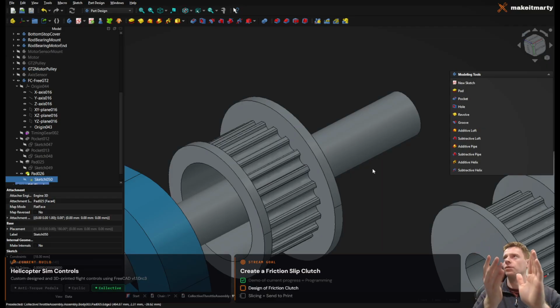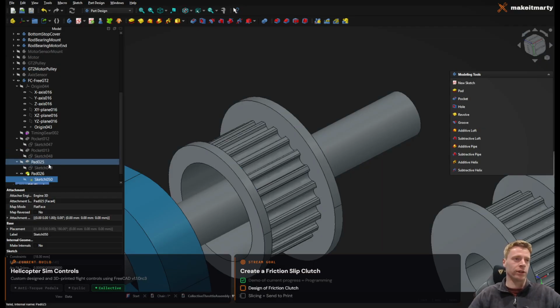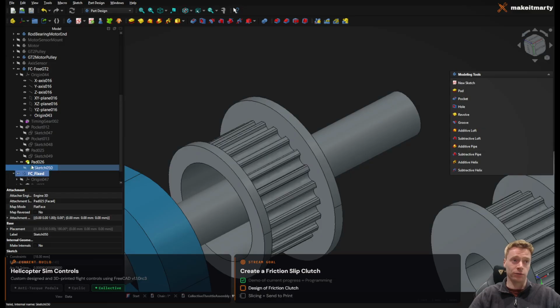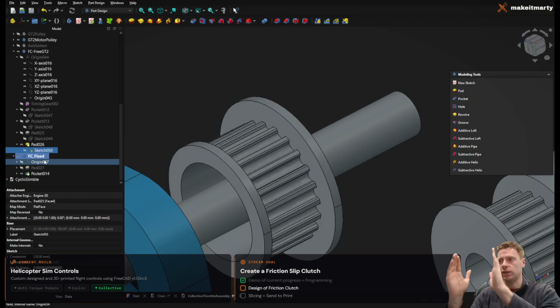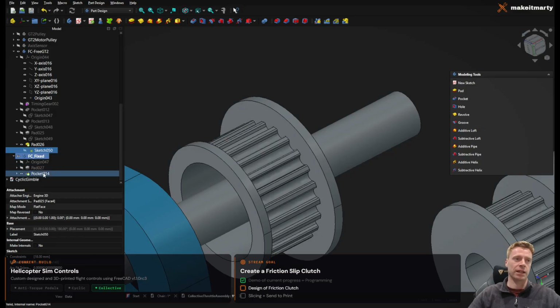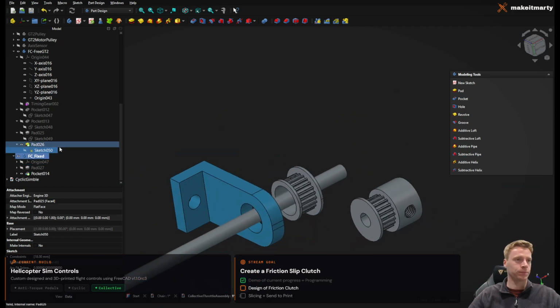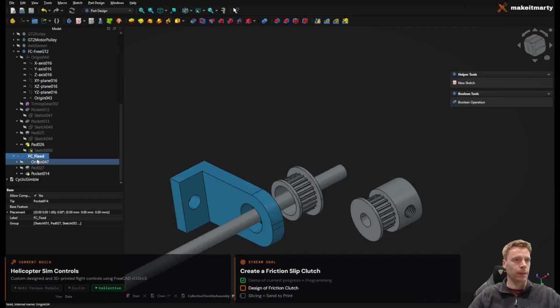I don't believe it happens with axes, but if you have a line with a distance constraint and then you move the object, sometimes that distance constraint can flip to the other side of the line. Truly infuriating. You can fix it by moving things in small steps, so the sketch solver doesn't have to solve it all completely. But yeah, things to pull your hair out over.